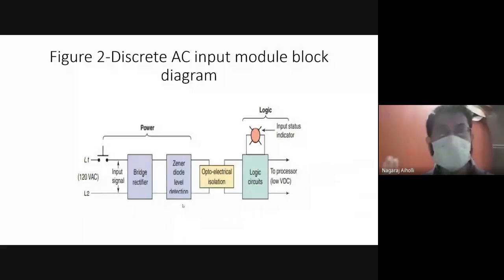As I told you, there is a Zener voltage for the diode when you change the polarity of the supply voltage, that is, when you apply the voltage in the reverse direction. When it reaches a particular value called the Zener voltage or the breakdown voltage, what will happen? Some magnitude of current flows which is more than the reverse current, more than the leakage current that flows when we initially start to apply the reverse voltage.